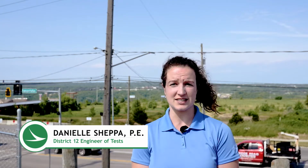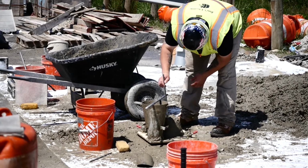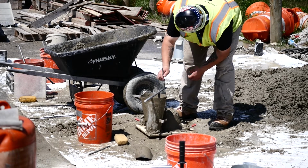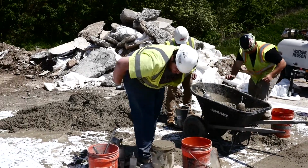One of the first tests that we do with concrete testing is we test for the slump of the concrete, and this is important with the understanding the consistency and the fluidity of the concrete as it's incorporated onto the project. It kind of varies depending on the type of work that you do, so whether it's structural concrete or pavement concrete, our slump ranges from about 1 to 5 inches. Again, depending on the type of work. The slump of the concrete is important to test throughout the work because you want to make sure that the concrete is consistent.